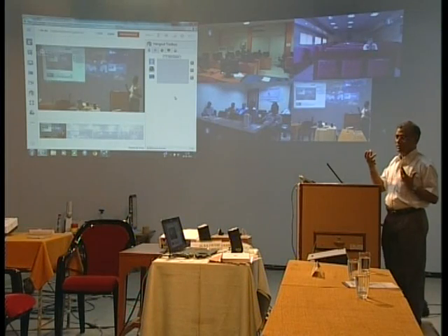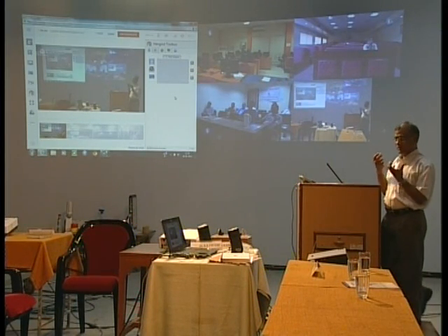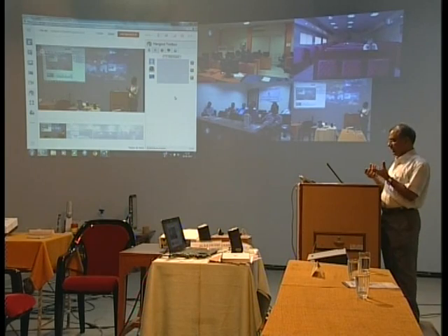So if you look at all these things, if I summarize everything, premix is good from the point of view of efficiency, but bad from the point of view of NOx, noise, knock. Diffusion is not good from the point of view of efficiency, but good from the point of view of noise and all that. Diffusion gives smoke, premix does not give smoke. So you cannot say that I want only premix, I want only diffusion. Both have their good and bad points. So the engine management system has to mix both of them to the right level and get good efficiency and low emissions together. So that is what the engine management system does.